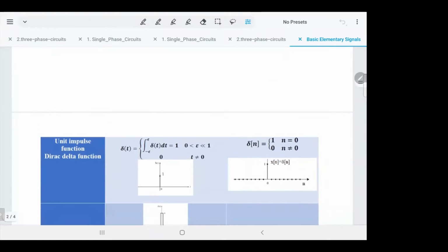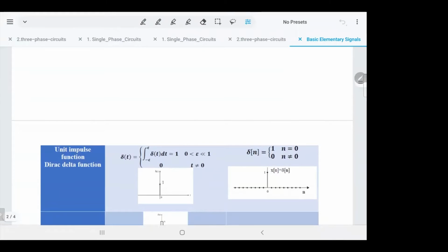The third one, very important, used in the analysis a lot, is the unit impulse, and sometimes it's called the Dirac function. I think you have it in math. What is that? This is like a sudden change in no time, in a very small time. Like if you get a hammer and hammer something, just in 1 instant, and that's it. There is no signal anymore. It happens instantaneously, a huge part. Ideally, you can say it's equal to infinity in 0 time, but of course, practically you can't have that. But this is the ideal impulse.